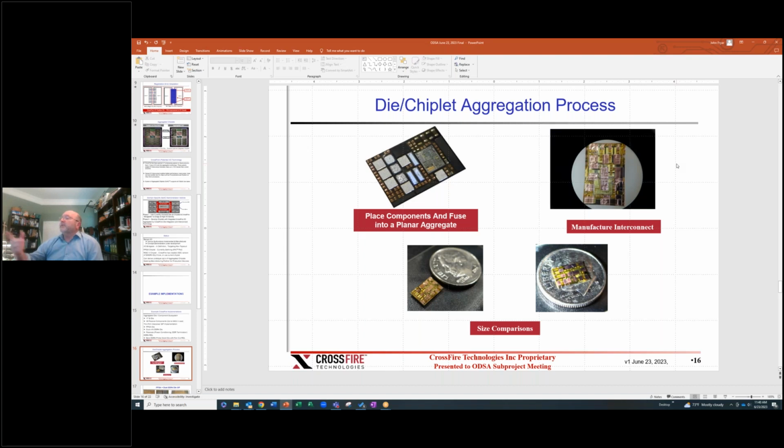And just to give you an idea about the size of this particular item, we like small because it's good for yields. This is a semiconductor process, so in volumes you get the economies of scale of semiconductor processing. In a 12-inch process, putting down 4 layers of metal, vias, this is going to be pretty economical.